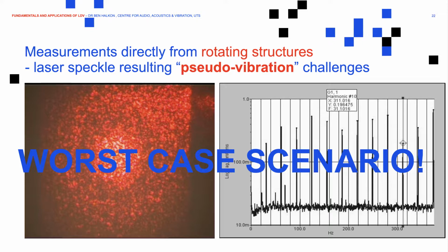And we're only really focused on a small area of this on our photodetector. We look at one or two speckles. Each one of these speckles has independent amplitude and phase. We can fix the amplitude problem, it leads to signal dropout, but the phase problem we can't resolve. And in the measured signal, effectively for a wheel that rotates without much vibration, in the time domain the signal looks like this. So you can see these artifacts that repeat pretty much exactly once per revolution.